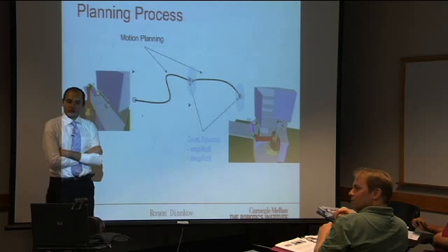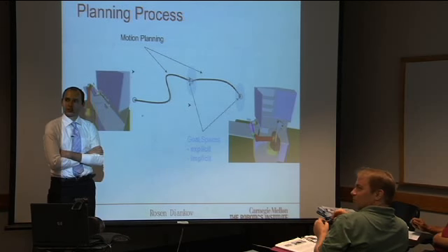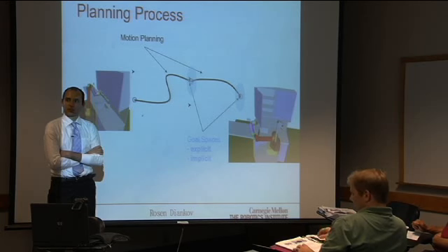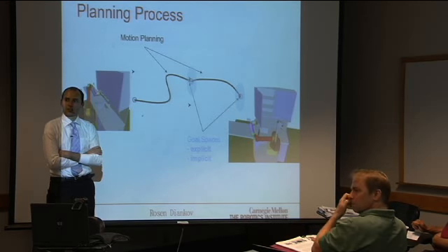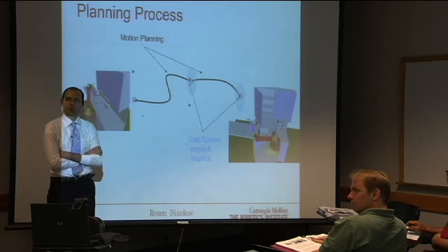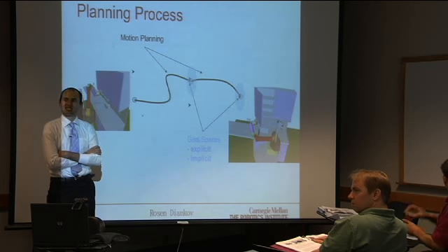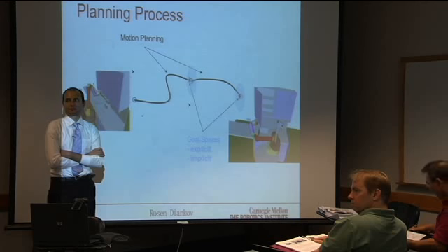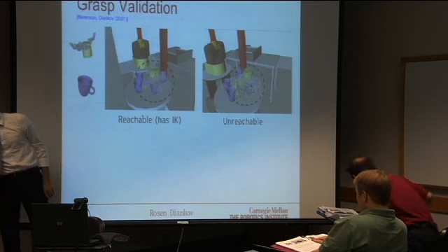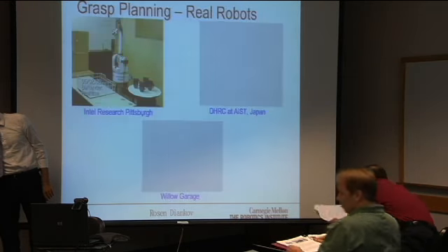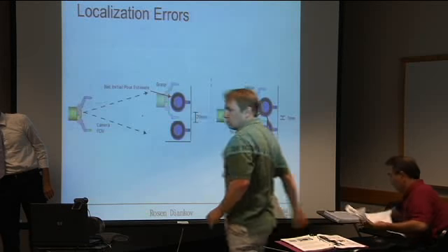I wanted to also ask you about the perception planning, where you stick your camera. The other body of work that I was thinking of a great deal when I saw that was the tracking community. There you've got a target you're trying to track, a lot of noise, and uncertainties, and you think about information filters and active tracking, where the shape of your uncertainty or covariance matrix would determine where you want to aim your sensor to reduce that uncertainty.